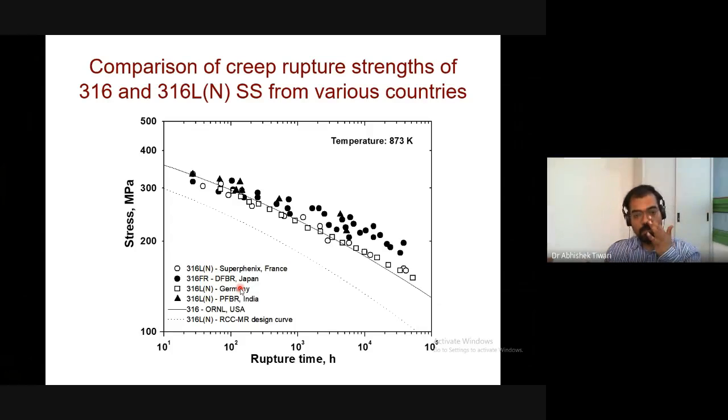It's called the heat. So for example, if you make one billet or one slab out of a caster, that is one heat. You make steel either by electric arc furnace, or by Linz Donawitz furnace, or LD furnace, or basic oxygen furnace. In one go, the amount of steel you make is called one heat, and that usually has the same chemical composition. But in the next heat, even if you are making the same material, the composition may differ a little bit if you are not doing a secondary refining process of the steel. So these are different heats of a steel.